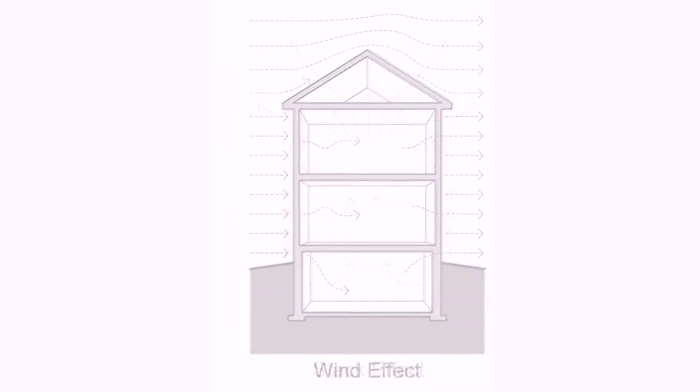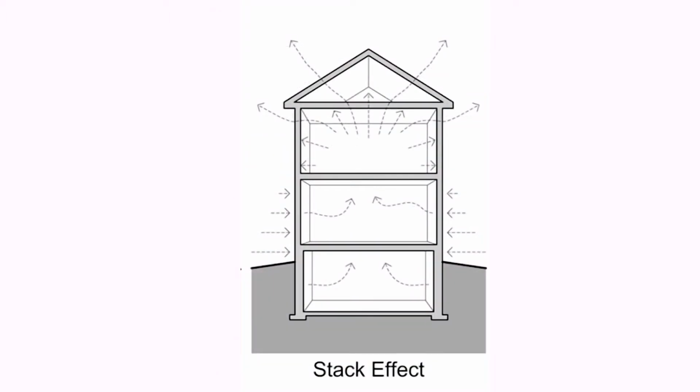Next is the stack effect. The stack effect is often misunderstood, but what it is, it's basically the buoyancy of heated air that rises up. And as it rises up, it increases the air pressure in the upper level of the structure and decreases the pressure in the lower level. So in essence, what you have is the same effect as wind-driven pressure, or wind blowing against the structure.